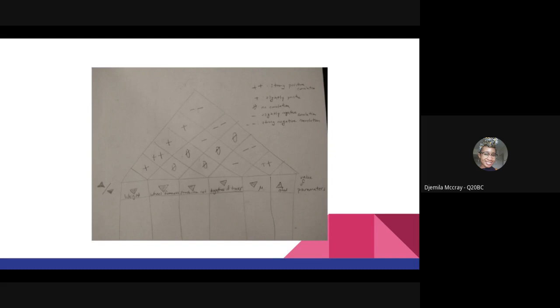And then if we're looking along the x-axis where I listed out each of the design parameters, I added an up arrow or a down arrow, comparing what we would want our ideal skate to have. So for example, ideally we want the weight to be a lower value. We'd want the tightness of the trucks to be low, because if the trucks were too tight, then the wheels would turn slower, and you can't turn as well. And we want the speed to be high because the user wants a skate to move them quickly.